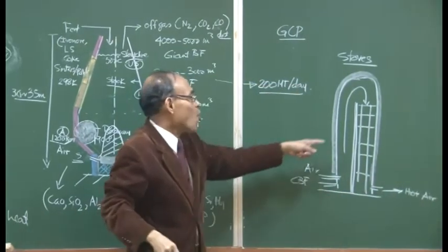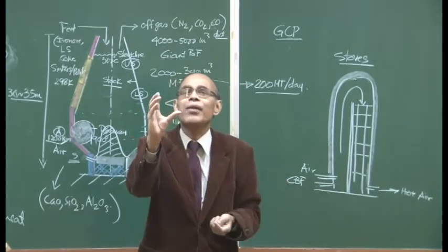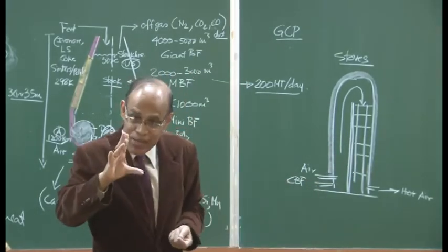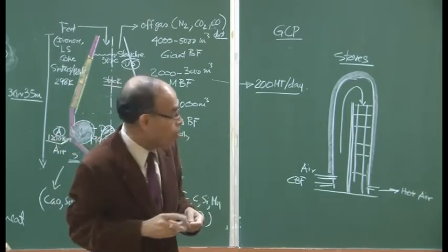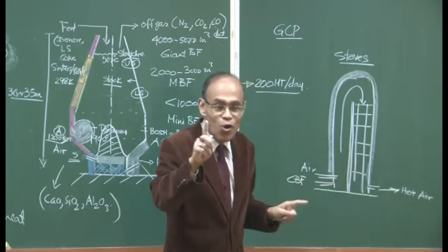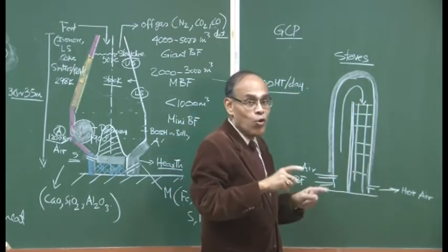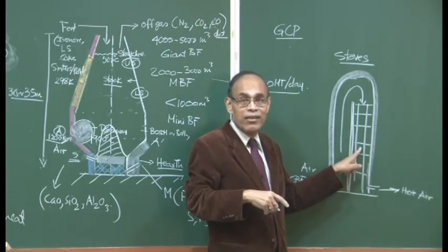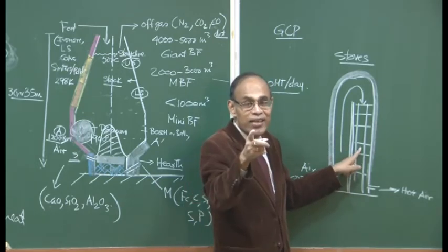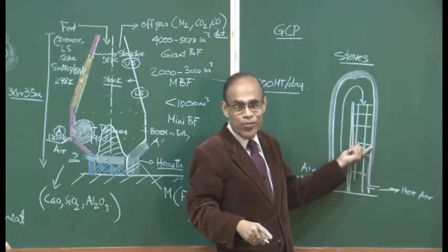So, this is going to be operated for, these are brick checker brickworks. These are highly porous ceramic bricks, light bricks because you have to buy less amount, and they are porous because they have surface area. For heat transfer, we all know that the hot gas going out after combustion through this will yield its heat to the brick, and that yielding of heat is directly proportional to the exposed surface area, which we know from our fundamentals of heat transfer.